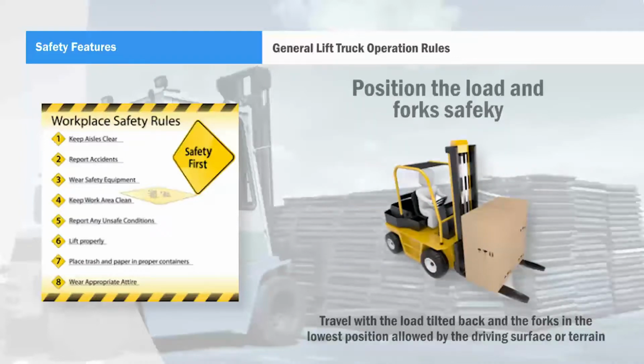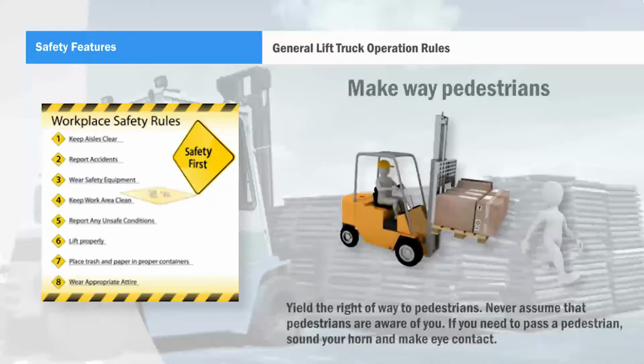Position the load and fork safely. Travel with the load tilted back and the forks in the lowest position allowed by the driving surface or terrain. Make way for pedestrians. Yield the right of way to pedestrians.